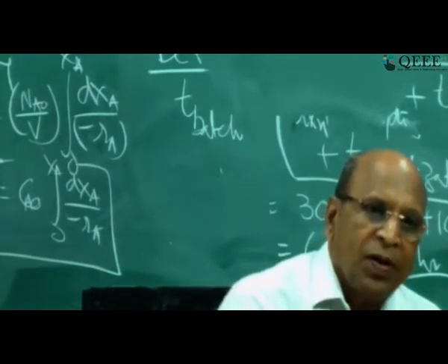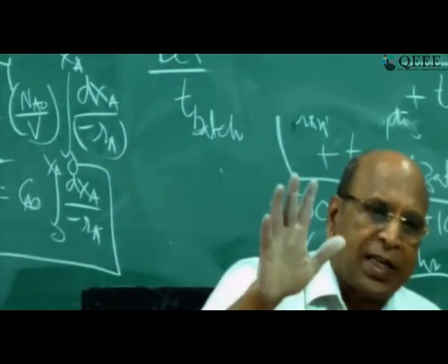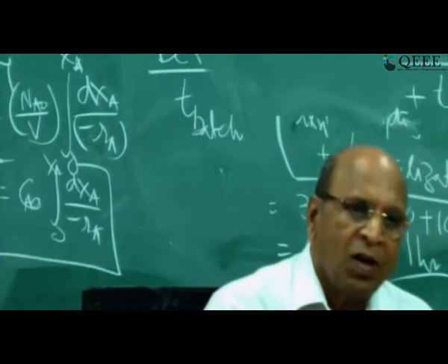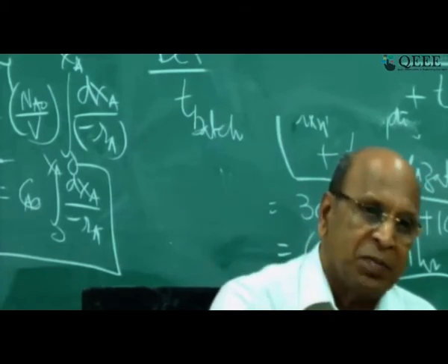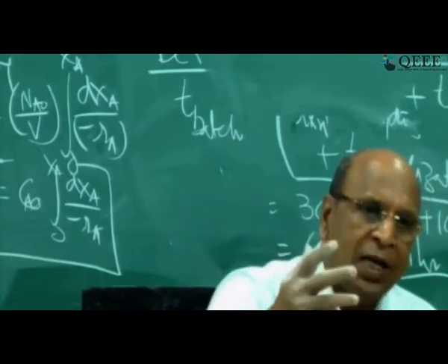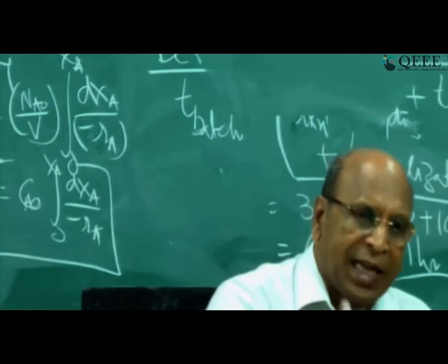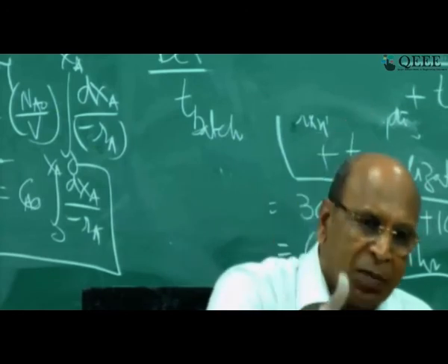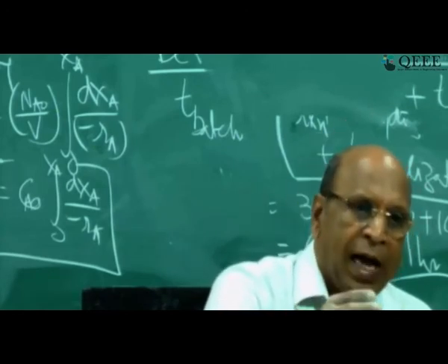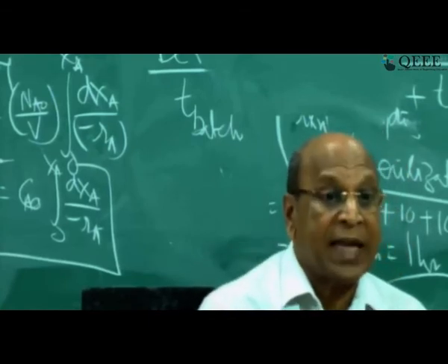Can you see any advantage of using plug flow in any field, when compared to mixed tank reactor? Oh yeah, I answered one question also. For all gas phase reactions, plug flow is the best. Because the gas phase reactions are very fast, you can provide that residence time in a plug flow reactor at high velocities where axial mixing can be almost 0 and radial mixing can be infinity. Good radial mixing can be there for gas phase reactions.